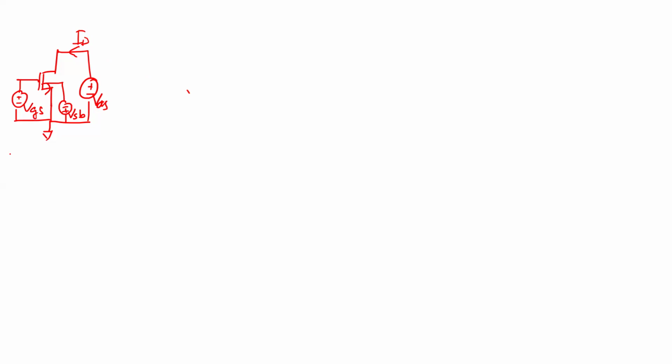then obviously the first region of operation is what? VGS less than VT. It's cut off, right? But we saw yesterday that it's actually not cut off. You are in subthreshold and you actually have very little current, but the gain is actually very high. Gain means you change the VGS a little bit, the change in current is much higher than when it is on. Okay, it acts like a BJT. So cut off or subthreshold.